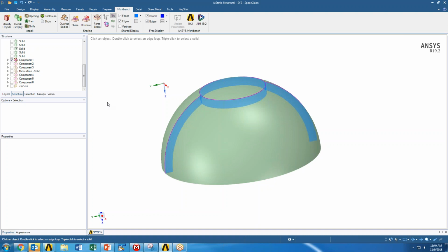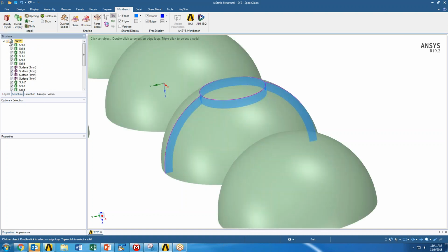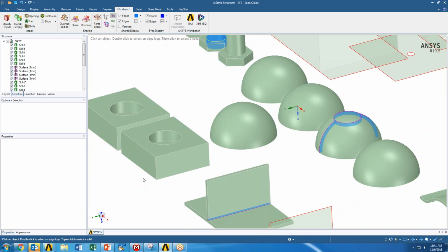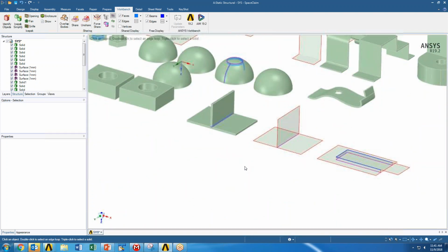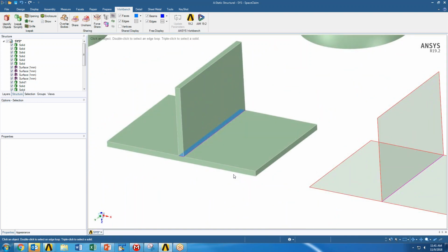There is the node merge capability in Mechanical. Oftentimes with the node merge capability, it's going to either miss nodes that should be shared, or when it shares the nodes, it's going to end up creating very poor quality elements. So the shared topology is a much, much, much better route. And this can be used for any number of things. I have a couple other examples where, let's say, I have a weld that's joining a body together. I can use shared topology to represent that weld joint. A weld fuses two metals together, so it's essentially one part. By using shared topology, it removes the need of having to apply contact, but it also is going to decrease the number of stress concentrations that are going to exist in the model.